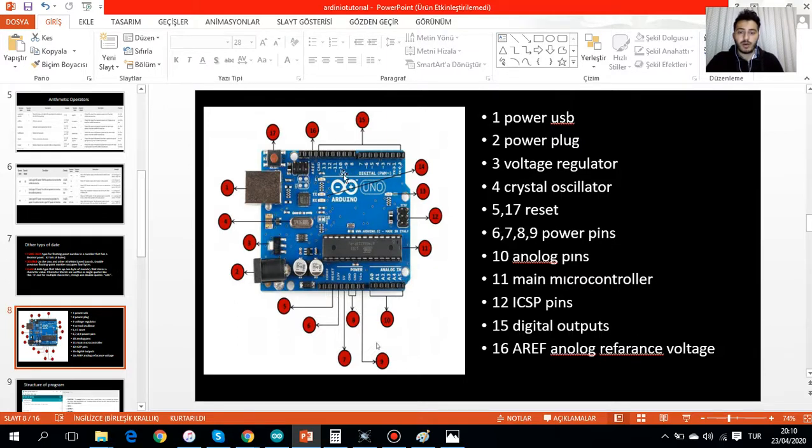But till now, we have worked on digital signals, and we know digital signals are 0 and 5 volts, high or low, 0 or 1. But today I'm going to talk to you about the analog signal, and an analog signal is a value between 0 and 5 volts because it is really live. Sometimes you might need to read a value from outside as an analog signal, like 4 volts, 3.5, anything else between 0 and 5, and then you process your program according to your analog signal.